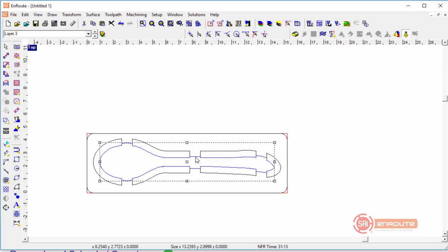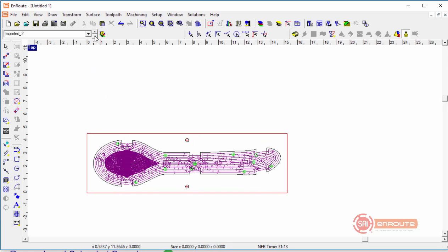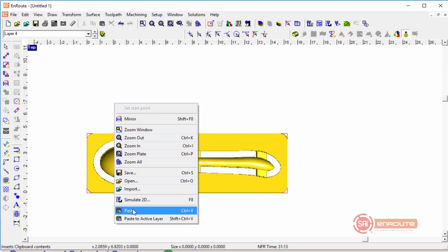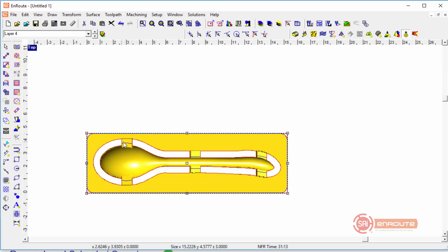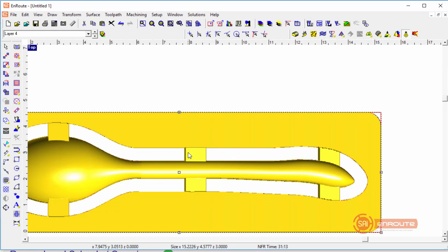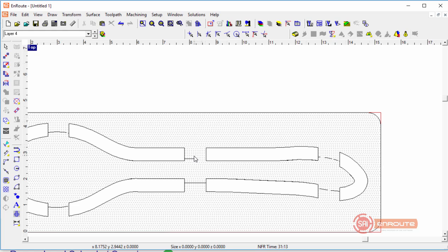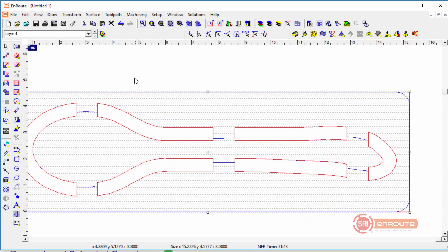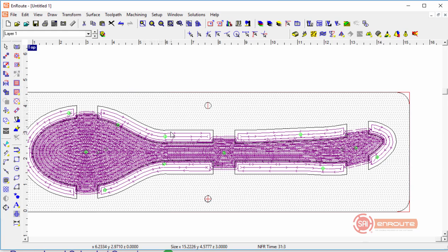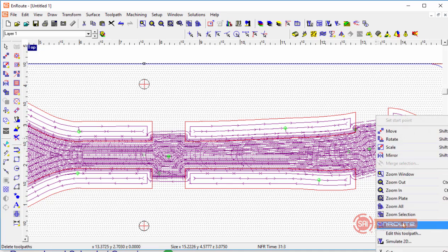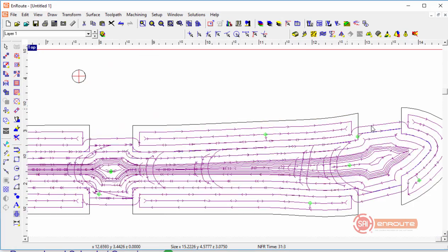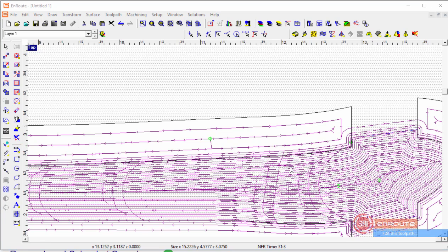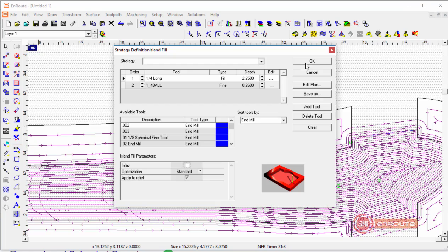I can grab my mask, select the relief and the mask, and now we have basically the same toolpaths to apply that we applied previously. So we can first of all go here and select this one, and this is going to be the ball nose one. We want the one with these 2. So I just came here to look at it for a second.